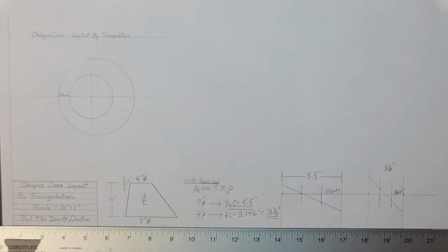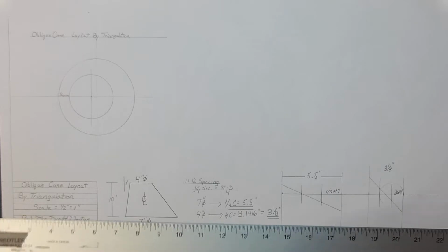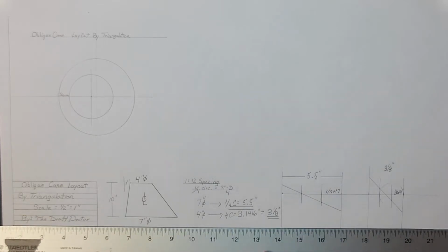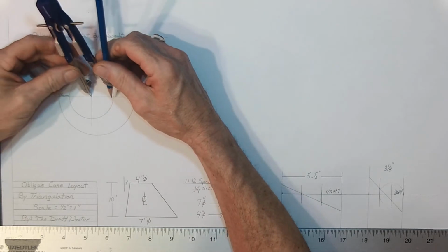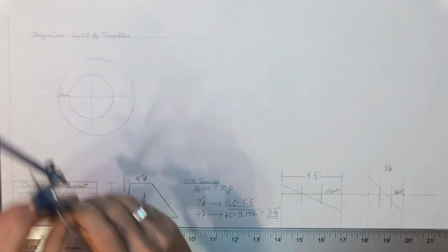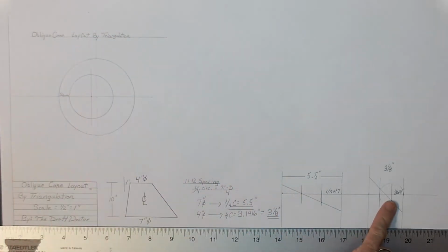I'm going to next have to lay out a working drawing. Now, a working drawing, we're going to lay this out from the plan view. I could lay it out from the elevation view. I chose the plan view today. Elevation view will be a different lesson, I suppose. Now, it's important for me to next divide the rounds on my layout into its 12 equal portions, so they will all equal the 1/12 spacing that I did earlier.